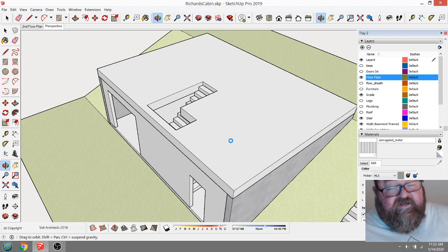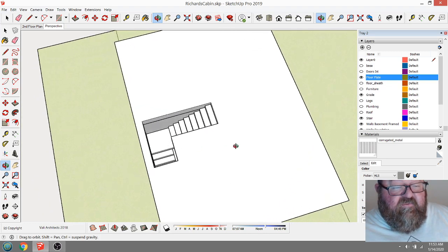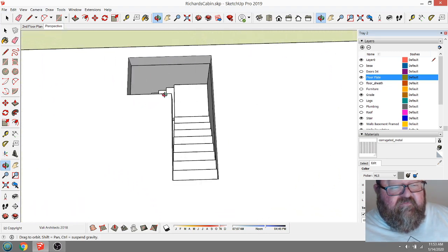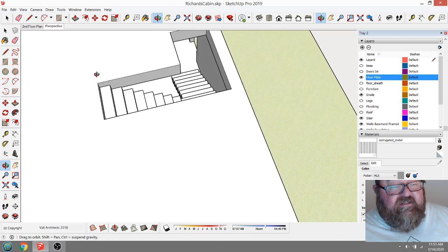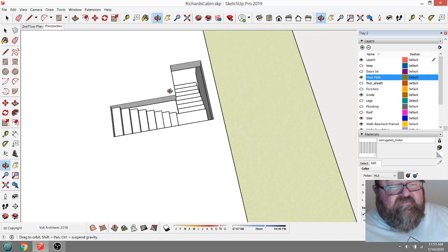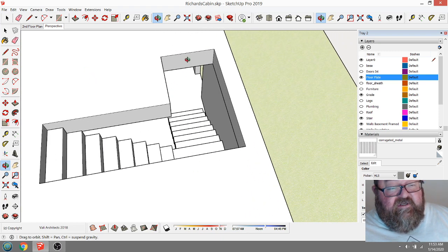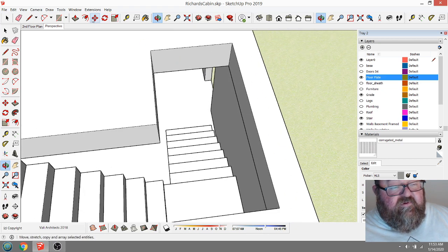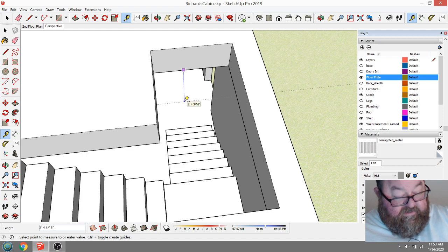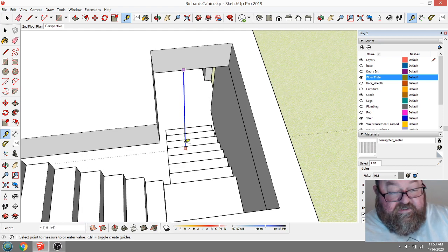But you can see here, based on the stair going down, you can see the kind of room it takes up on the upper floor level, and you have this L shape because the code requires headroom on a stair of minimum of 6'8". So I usually like to leave a little more than 6'8". So if you go to that nearest tread, it's 6'10" right there.